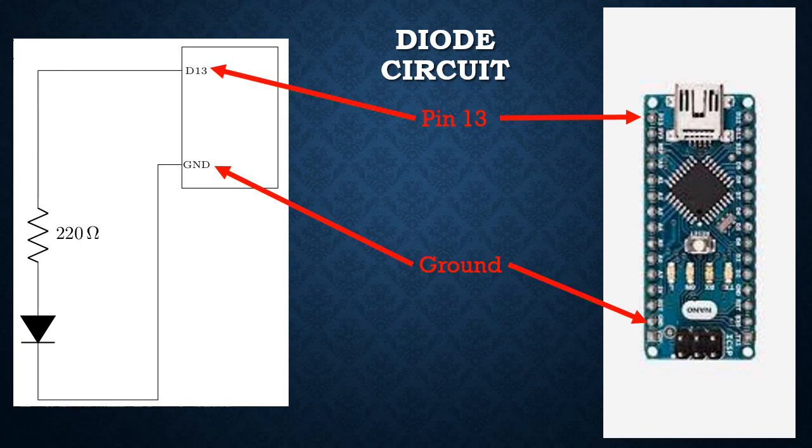Okay, so let's say, for example, you connect your wire that's at D13 down to, say, row 22. Okay, you pick a hole in row 22, one of the A through E holes, let's say. You put your wire into 22A. Then you want to stick one end of the resistor into, say, 22C.